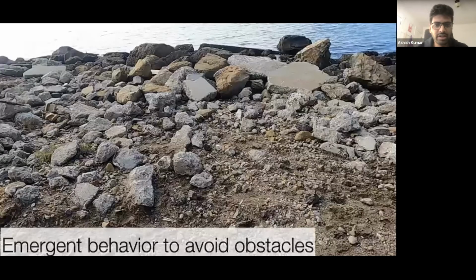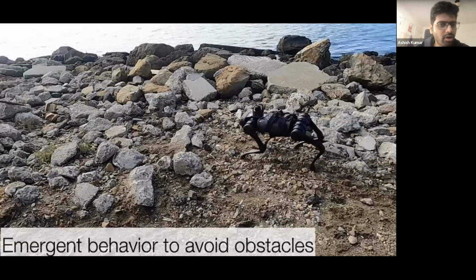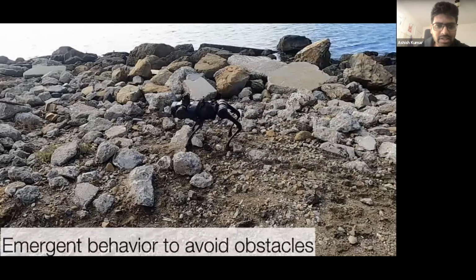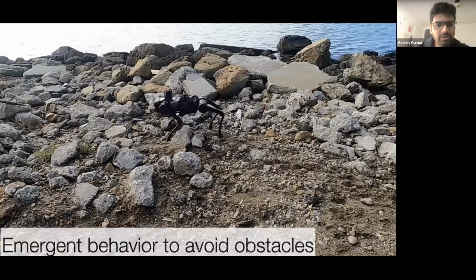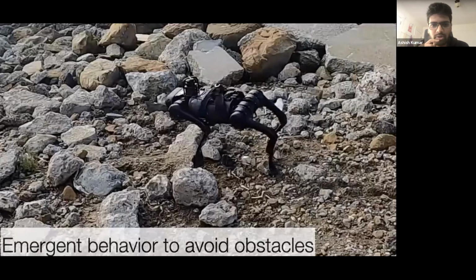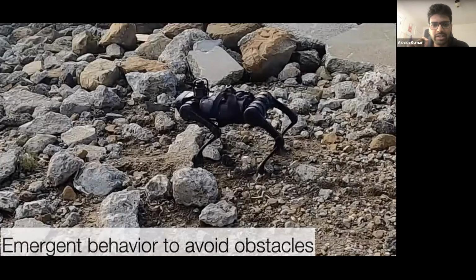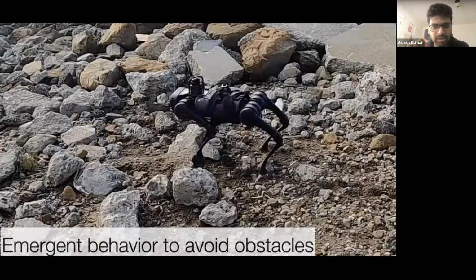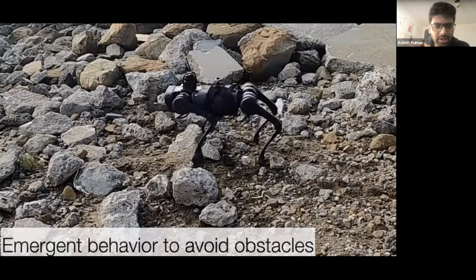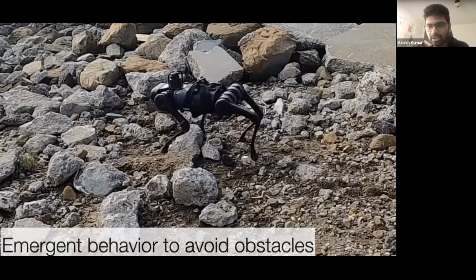So this is the first video that I showed in the talk. In this, the robot is trying to walk between these rocks, and we see that its feet get stuck and then it tries to get out of it. But let's take a closer and slower look at all 4 feet of the robot. When the robot gets stuck, instead of following a predefined trajectory, all 4 legs stop. And when the front legs adapt to this obstacle and get over it, we see that the rear legs right now will also start walking.